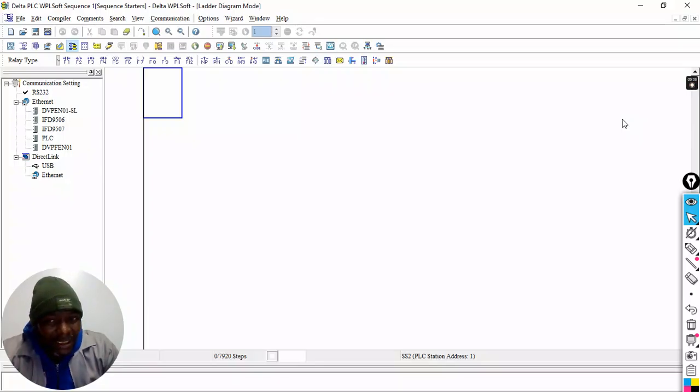Have similar characteristic currents, all right? The running currents. Now, what are you going to set the overload to? Are you going to set the overload to the sum of the two individual currents of the motors? Which would mean that if one motor is running and there's an overcurrent situation, the overload won't trip, because the two motors have one overload, and it has been set to the sum of the two. It is a risky situation that can destroy the motor.